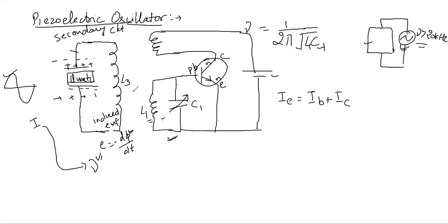So now what would happen in this case? यहाँ से जब कभी भी, now not only this L1 and L3 are inductively coupled. This L1, if I call the second coil as L2, L1 and L2, they are also inductively coupled with each other. So what would happen? Every time there is a change in the current here, there will be an induced EMF produced here also.